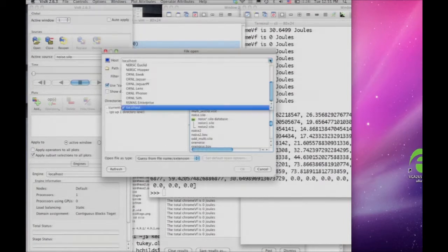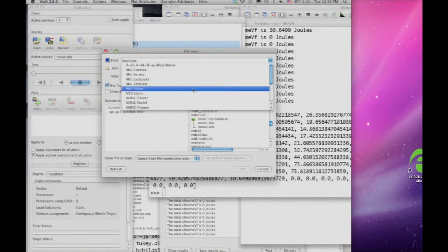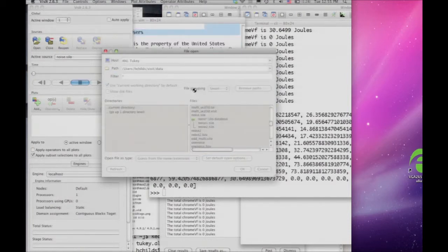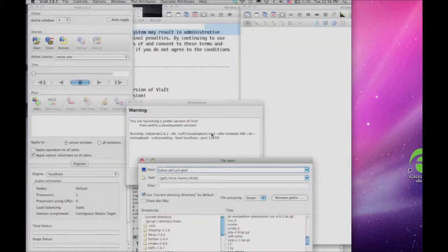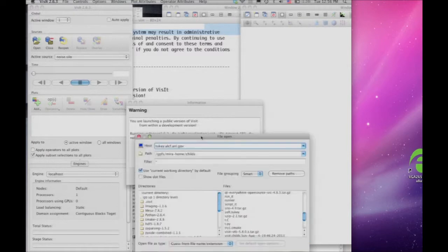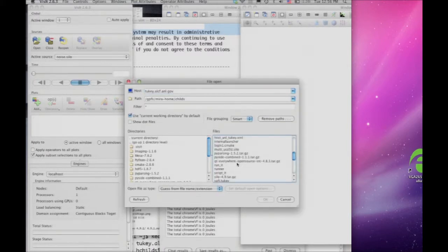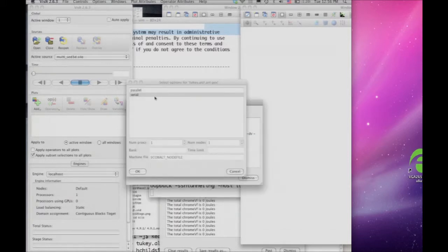And I think what's really neat about this is that it's quite a small script. I should comment, if you want to learn more about the VisIt scripting language, if you go to Controls, Command, you can put in Python scripts that you use regularly and turn them into macros to make new buttons out of VisIt. But also, if you want to learn how to use the command line interface, you just press the record button. And then if I were to delete that plot and then say stop, it tells me what the equivalent command is. So it records all of your commands and gives you the equivalent scripts.